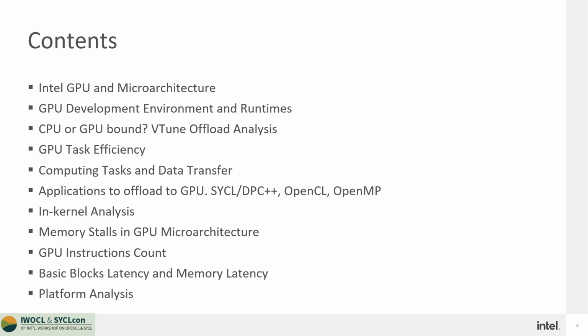Also, we'll take a look at applications written with SYCL DPC++, OpenCL or the OpenMP offload model. Then we will observe some in-kernel analysis, memory stalls in GPU microarchitecture, GPU instructions, and memory and basic block latency analysis in the tool. And finally, we will observe some platform analysis on the system.